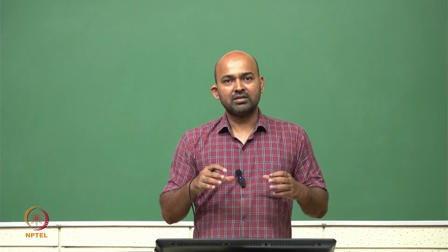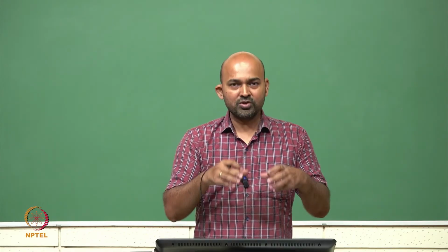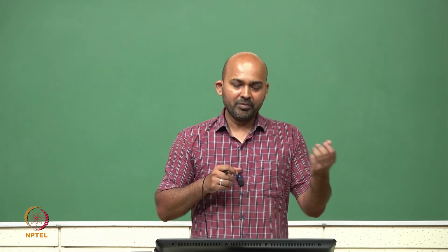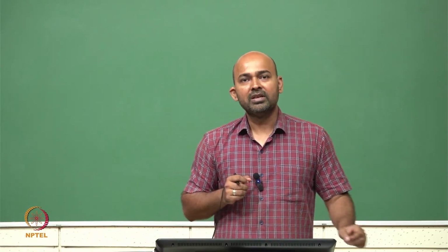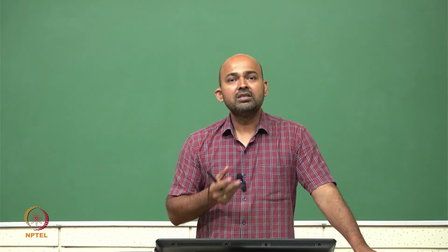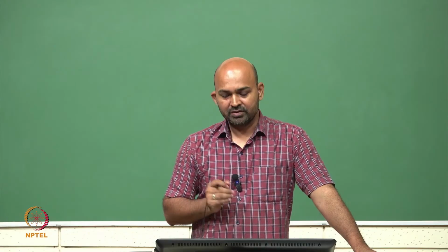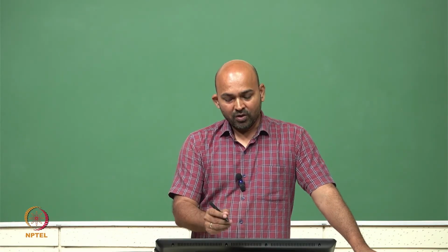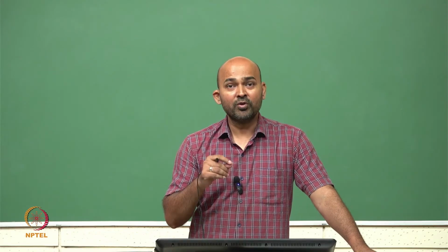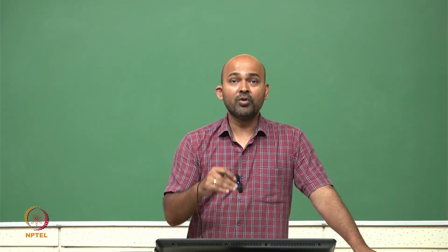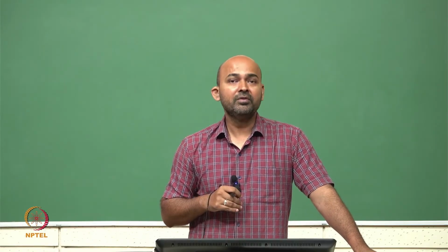However, when we want to fabricate this circuit on the actual hardware, we buy this 47 kilo ohm resistance from the market. This comes with a tolerance which is 5%. So now, this 47 kilo ohm is no more a 47 kilo ohm, it can be a 44.65 kilo ohm or it can be a 49.35 kilo ohm.